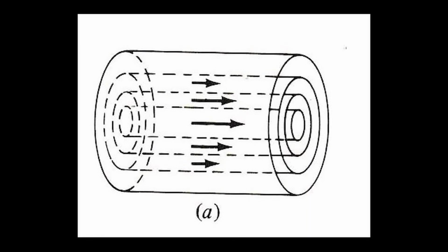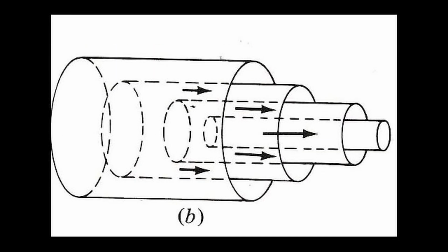In laminar flow, no mixing occurs between adjacent layers and occurs at low average velocities, A compared to B, and as we can see from A to B, that is the flow pattern followed. In a non-viscous fluid, the pressure drops as the tube narrows and average velocity increases. In viscous fluids, additional pressure drops occur due to the work done against viscous frictional forces.